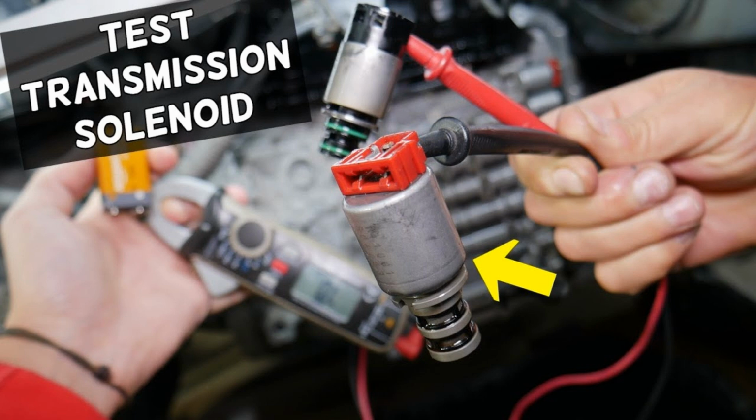Regulator solenoids. Already since the mid-90s, engineers again thought about improving the solenoid and created a new type. Such regulator solenoids were developed on the principle of a valve. Depending on the specific type of impulse coming from the ECU, the curved internal cross-section of the device opened and closed the lubricant flow. Here the electric current was supplied with a certain frequency and intervals. Such solenoids are separately categorized into ball solenoids, spool solenoids, three-way, four-way, and five-way.